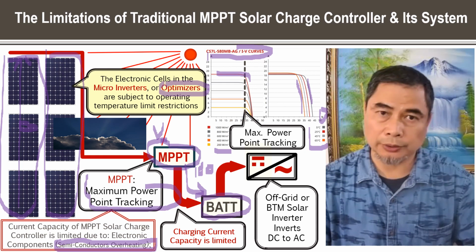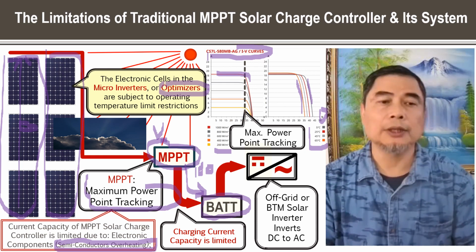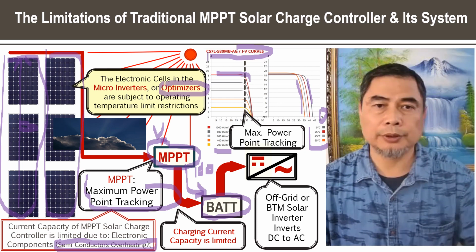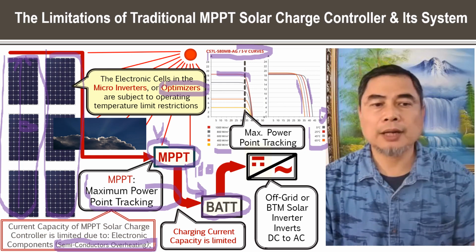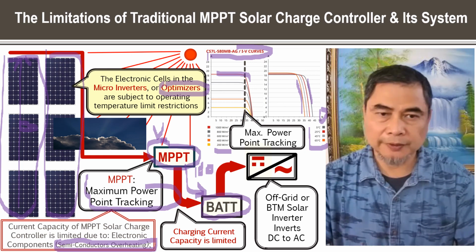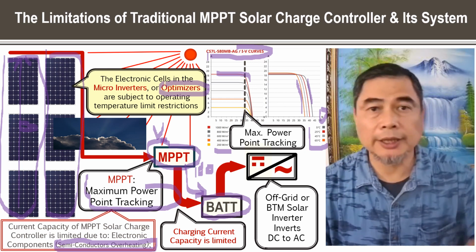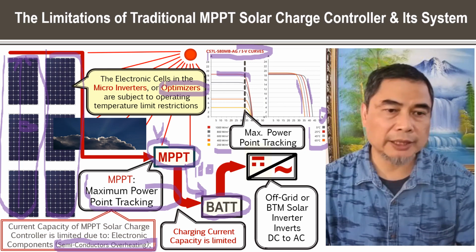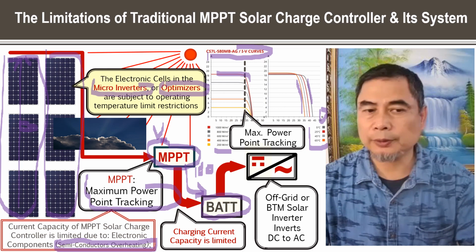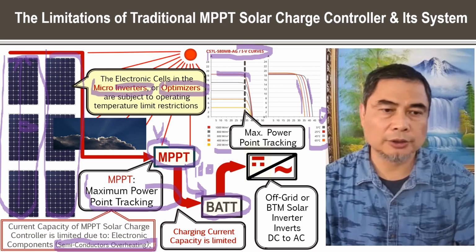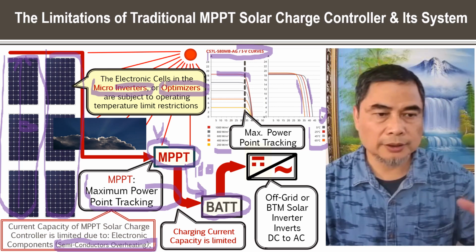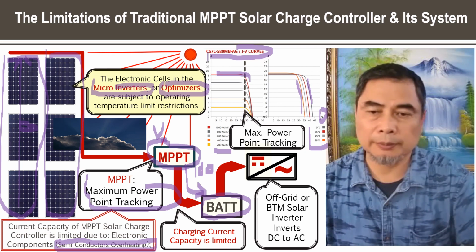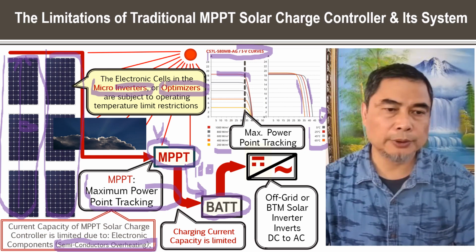You can put them indoor, have proper temperature humidity control. Another thing is that some of the manufacturers build in micro inverters. Say you have a string PV system, and the voltage can be really high, 1,500 VDC. And they build this micro inverter inside, but it may not be used in the MPPT solar charge controller system. They say, okay, because when you put lots of panels in series, one can be affected by other panels' malfunction. So they try to build a micro inverter.